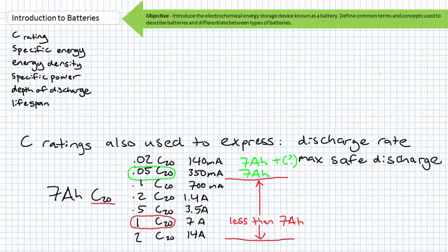For example, a 7 amp hour nominal capacity battery that can be safely discharged at 4 times the C rating can safely deliver 28 amps, whereas one that can deliver 8 times the C rating can safely deliver 56 amps. Again, with your understanding of the inverse relationship of battery demand and supply, one could be reasonably certain that batteries, regardless of the magnitude of the safe discharge, will deplete themselves significantly faster and deliver significantly less energy than the nominal 7 amp hours when discharged at such high rates.